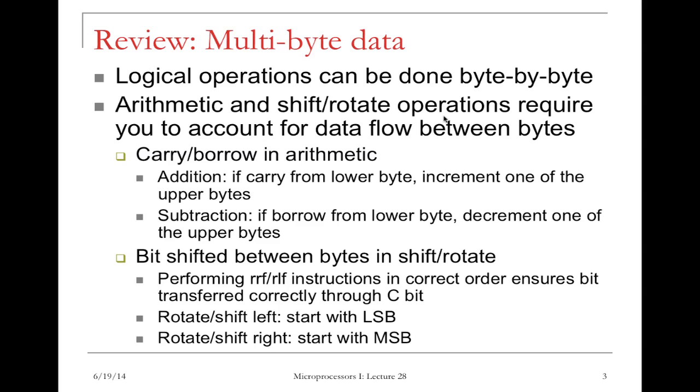Logical operations can be done byte by byte, and arithmetic and shift rotation instructions are required to account for data flow between bytes. For addition, we'll also consider the carry bits. If there is a carry from the lower byte, you increment 1 in the upper byte. This is for the multi-byte counter, for example.